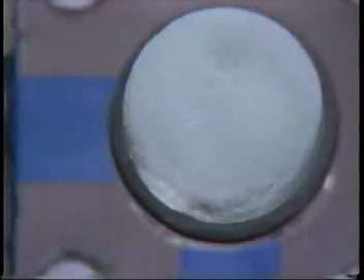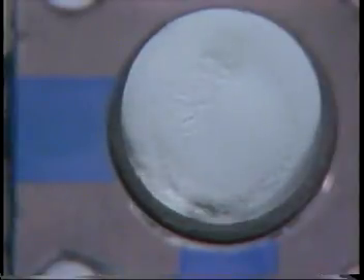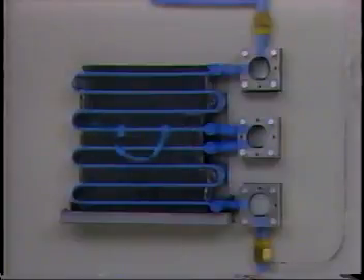Naturally, it is still a gas when it leaves the evaporator. In other words, if there is only a small amount of refrigerant in the system, it completely turns into a gas by the time it reaches the middle point of the evaporator, and no evaporation occurs near the exit of the evaporator. This means that the refrigerant is not taking heat from the air.